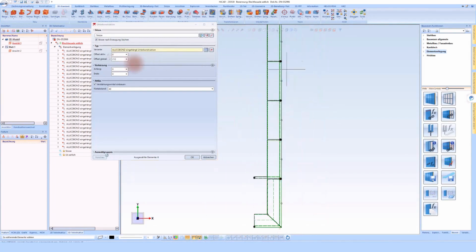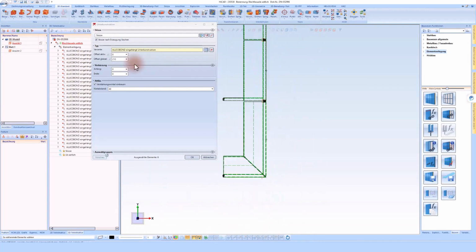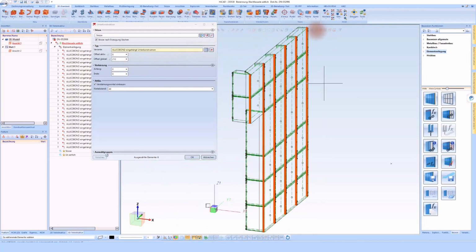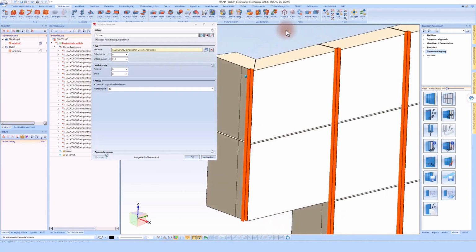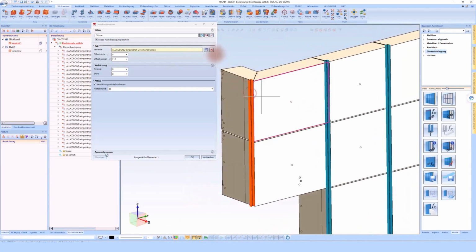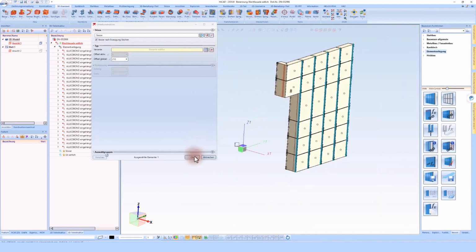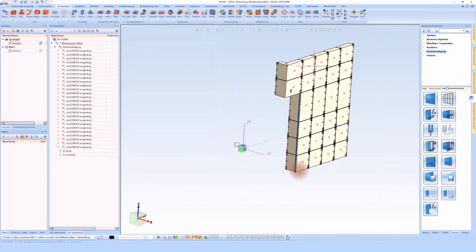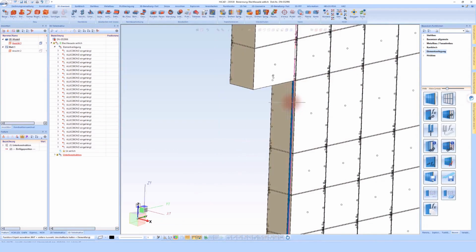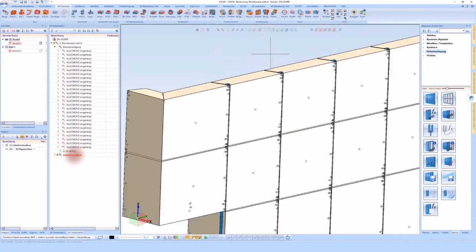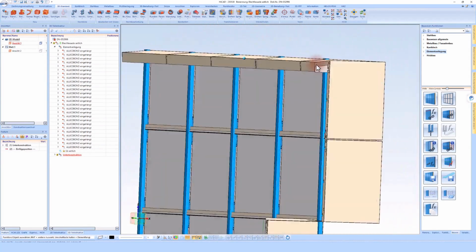I still assign my marker, and from the sheet facade I see that I do not need this sketch, which means I can delete it and incorporate these profiles. In this case, you can see here that I still need to adjust this profile, and here I would need to adjust the length.